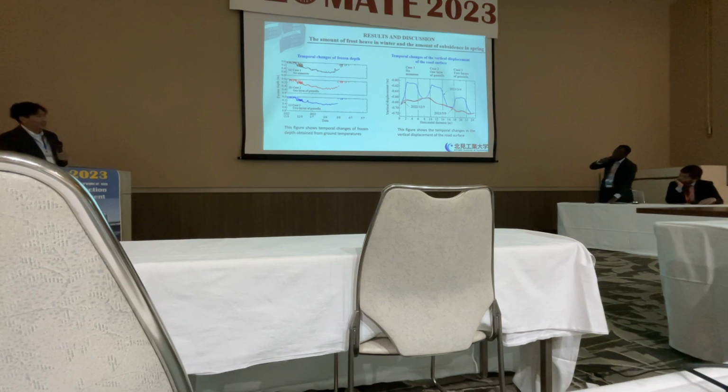Just one recommendation also. This one is just one season, one winter. What will be the effect of two years? Yeah. Also, my supervisor, my professor wanted to repeat it next year. This time we had some failure of the compaction. We used the hand guide roller. It's not enough to compact the subgrade and subbase layer, and next year we will repeat it. Thank you very much. Thank you.